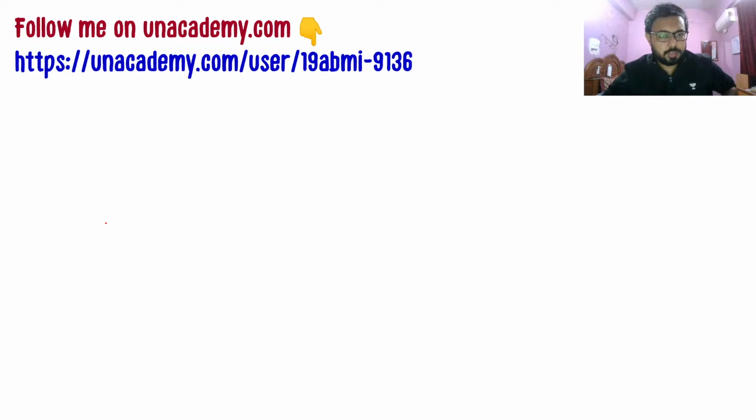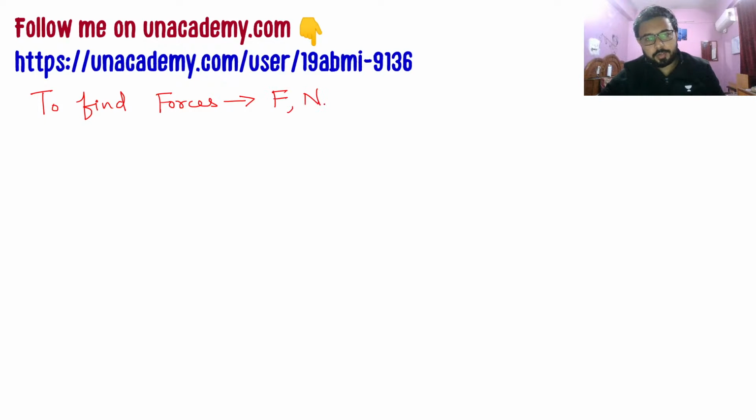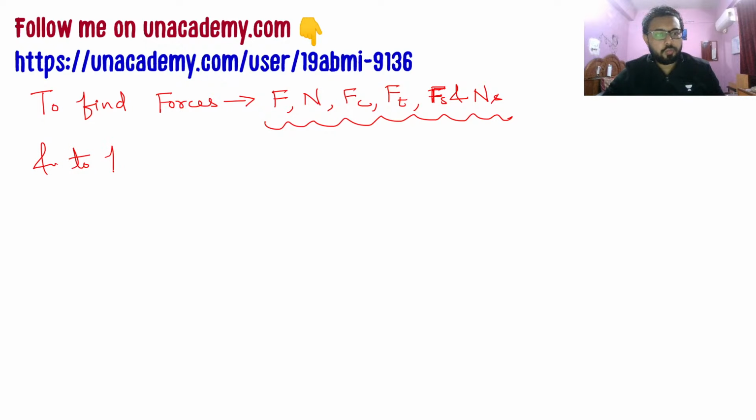So let's discuss the Merchant circle here. I will write the forces it is used to find: F, the frictional force; N, the reaction force on the friction surface or tool surface; and we have the cutting force, thrust force, shear force, and the normal force on the shear plane. So to find these forces and to find angles,